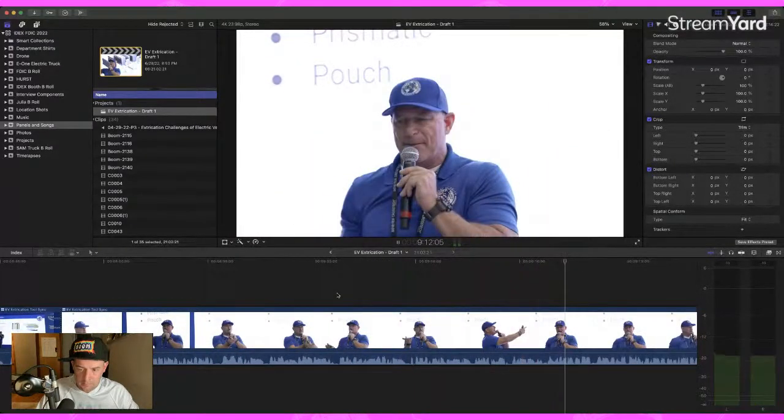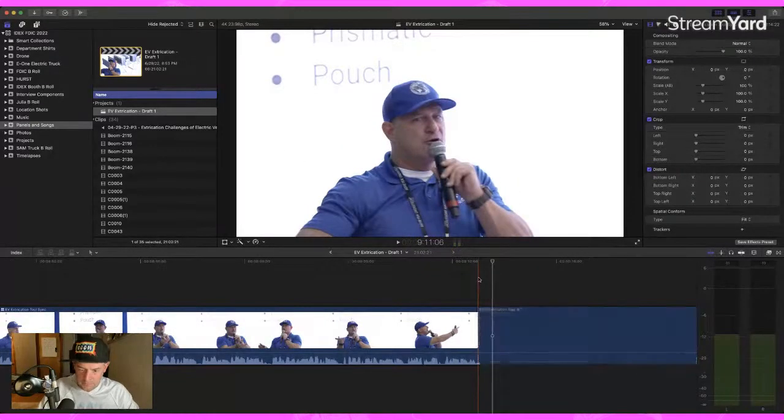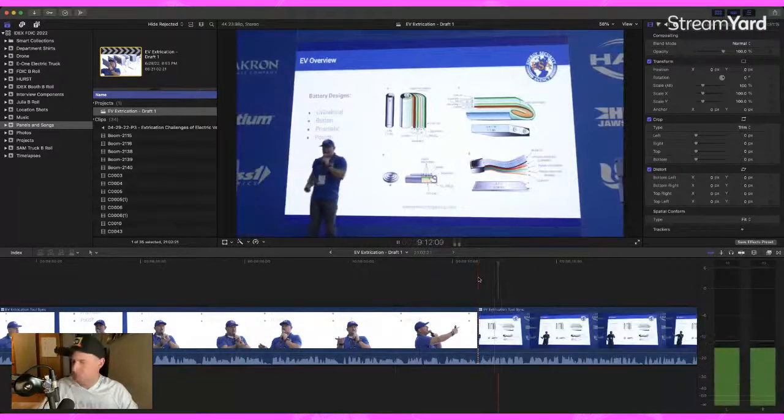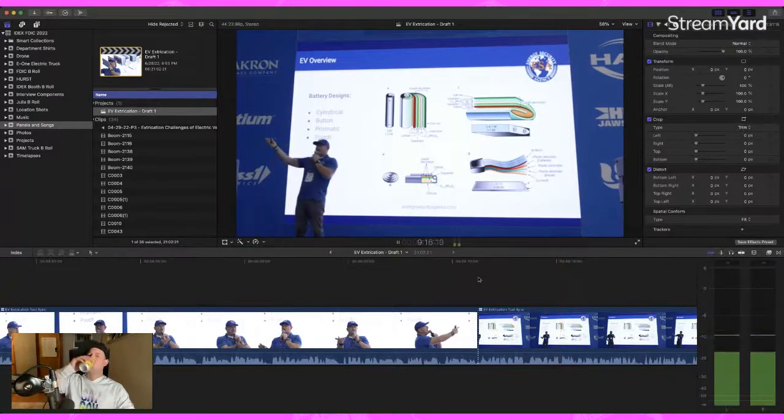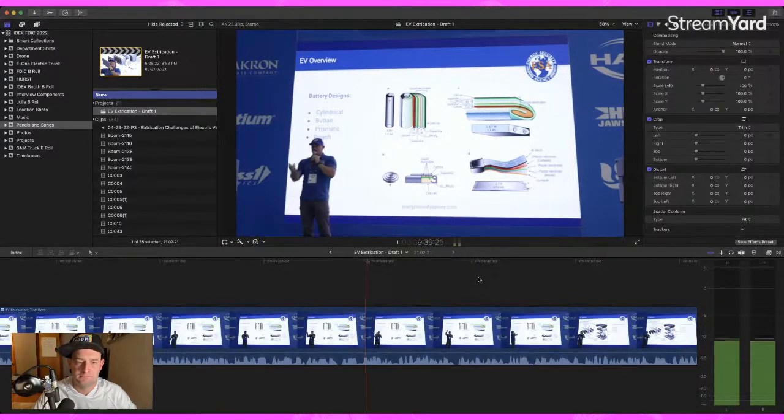Recent event happened out in California. Had a recycling center fully removed the traction battery pack from a vehicle, did all their protocol checks, took that vehicle, put it into a crusher, removed it from the crusher, placed it on the sled with all the other crushed cubes. It caught on fire because of a lithium-ion-based fire. Caught all the adjacent things on fire. Ended up burning 30 acres of wildland property. And the source of that fire was the low-volt lithium-ion battery. All right, all that. So even the little guy can get.